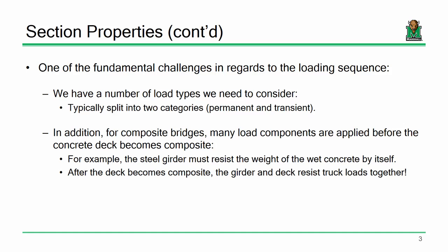First thing I do is I take the beams, I set them down, right? Okay, so what loads are the beams subjected to right then? What loads are they subjected to? What's that? They have to support their own self-weight, right? Obviously, all beams have to support their own self-weight. Well, what is resisting that load is the steel beam by itself, just the steel beam, okay?